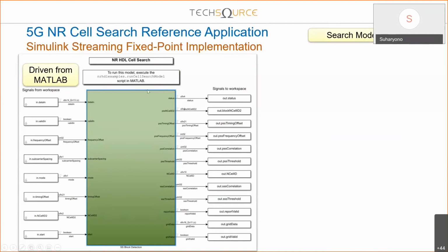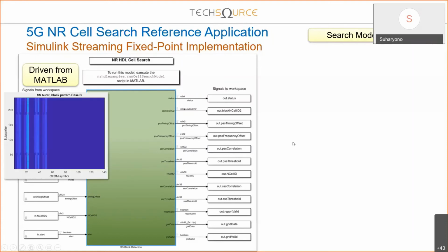You can inject the stimulus, the signal you design from MATLAB, and then you can compare the implementation with your MATLAB golden reference and verify the result.